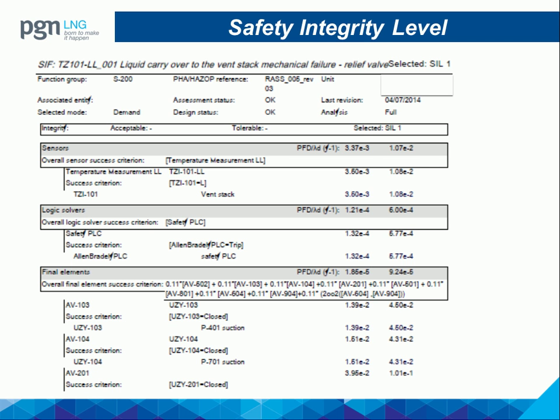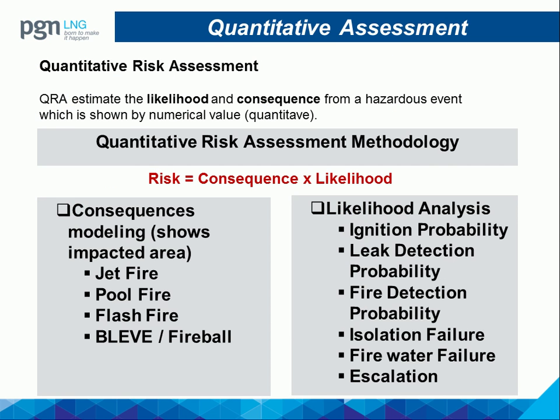From the LOPA assessment, we will see the safety integrity level assessment, which gives confirmation whether all the instrumented safeguarding that we use is indeed okay for the SIL that we assume. There are other details, but maybe you can get the point.